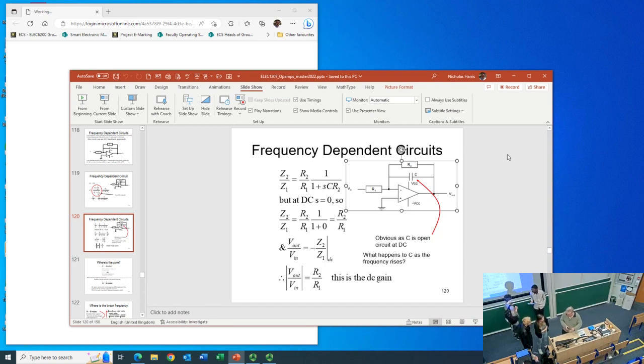Quite often you'll go down to 100 millihertz, 10 millihertz, 1 millihertz. I mean, how close is a millihertz to 0? You can keep going in orders of magnitude if you really want to, but all you end up with is usually a flat response. You just say, okay, obviously nothing horrible is going to happen in the remaining 0.0001 of a hertz. And you'll know from the equation anyway what you expect.